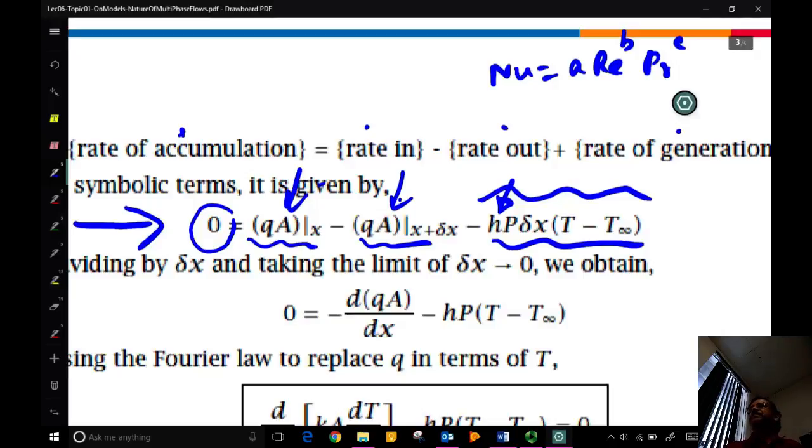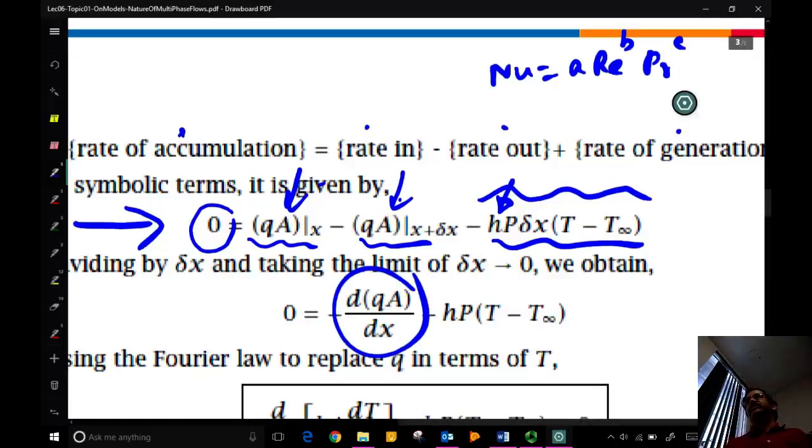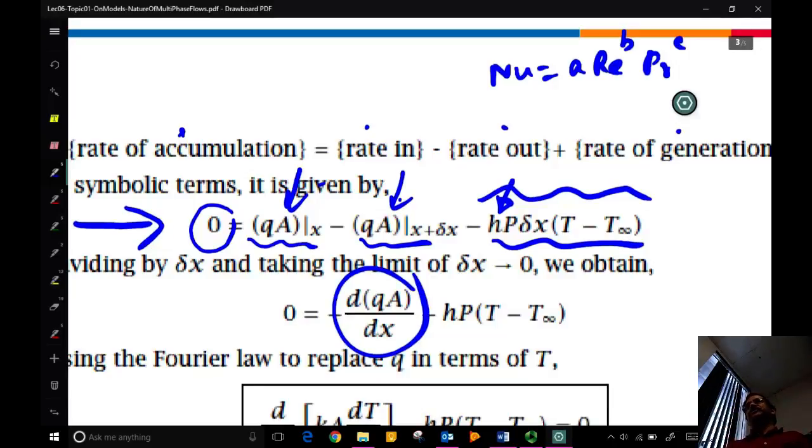So they're trying to make this problem one-dimensional? That's why we use delta x? We are trying to make this one-dimensional, but once you learn the tricks in COMSOL, it's so easy to make it two-dimensional. When it is two-dimensional, what would happen? You will have to have a bounding box in the y direction, perpendicular direction, and you will have QA at y and QA at y plus delta y, and so you will have a second order derivative in the x direction and in y direction. So it becomes a partial differential equation. Okay, any other questions?